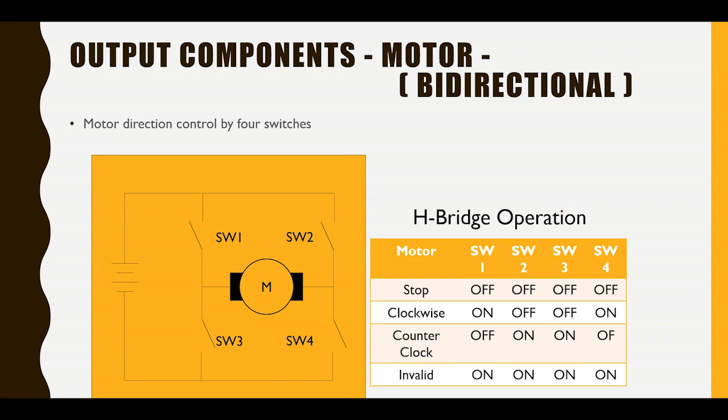All right, so if you want to keep on changing the motor between clockwise and counterclockwise, you could use this way of switching it. For example, the battery will still be the same, plus and minus, except that the direction of the current will flow according to the switch position. So in this case, let's say you have switch 1 and switch 4 on, meaning the current will flow from here through the motor and then, all right. So that is the first position.